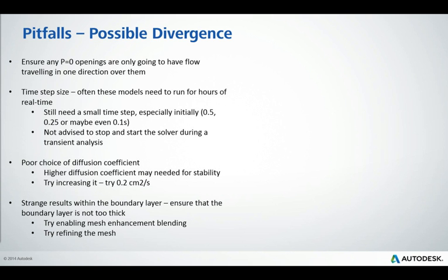Quite often we want to run these models for 20 minutes or more. If I was running one of these, I'd want to run a time step of maybe a minute and run 20 time steps and I'm done. But because so much is happening over time, the flow regime is constantly changing, we just can't do that. We need a pretty small time step.